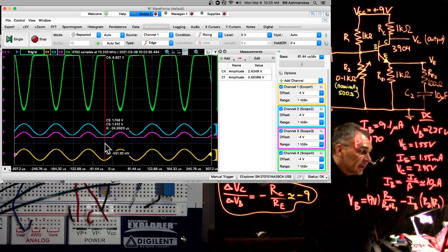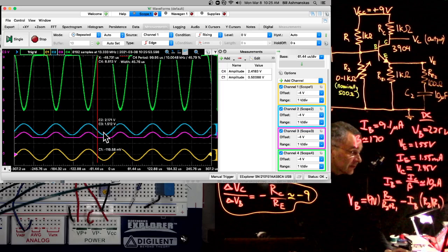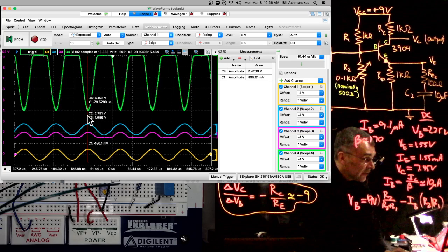Instead, just notice that the transistor does cut off down there, so the collector current is 0. That makes sense because VCC minus RC times IC is just VCC. So when we have this flat spot up here at 9 volts, the collector current is 0, and that corresponds to the transistor being cut off, which corresponds to the base emitter voltage being really small, smaller than a diode drop. I guess that's all we notice.